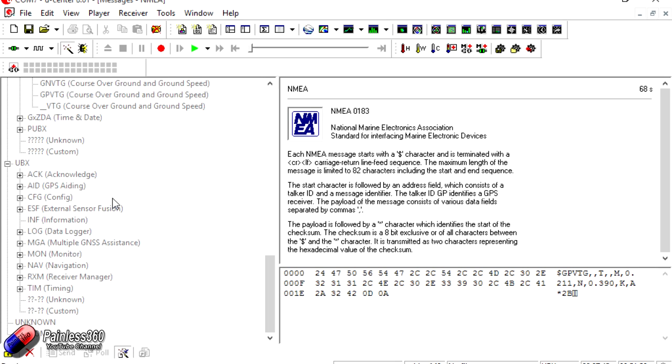So now I need to enable the uBlox messages that we actually want, and we only want 4 of them. And again, don't forget, all this is documented in that web page that we looked at. So if you're not sure about exactly what we're doing here, the way I'm doing it is the way I recommend you doing it. We're recording here on the laptop, and we've got the main PC actually showing the instructions. So we're going to go into Nav.